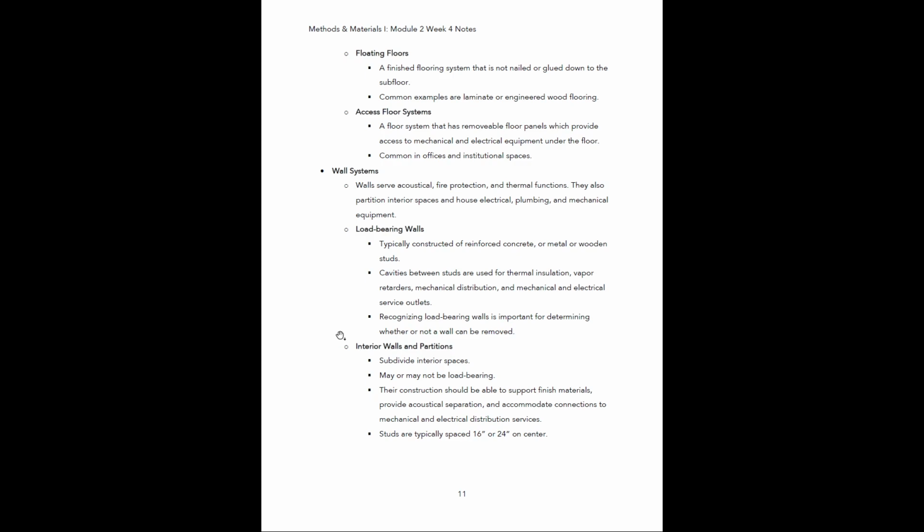But again, whenever you're doing a renovation, there might be a wall that you want to remove to make the space more open. But if that's a load-bearing wall, it might not be able to be removed. And if it can be removed, you will have to replace it with some other type of structure, whether that's a beam or something else, in order to make that open, because you still have to carry that load. So you have to be able to recognize it and know what you need to replace it with.